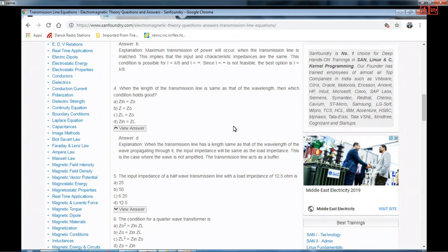But if the length of the wire comes out as hundreds of meters or even more at an operating frequency of 10 megahertz, 50 megahertz or something like this, then the line length is going to cause a good amount of attenuation. So a D flip-flop at very, very high frequencies using this is a difficult proposition. So we ask for alternative methods to get the delay flip-flop operation.